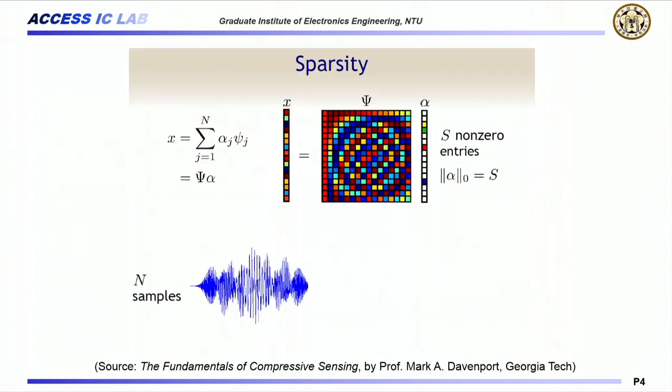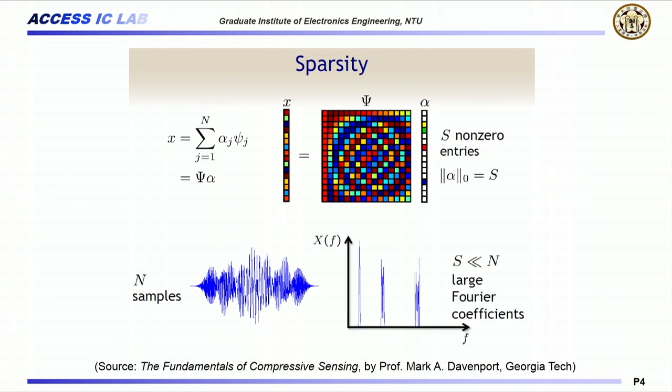One of the most important ingredients of compressed sensing is sparsity. This time series signal shows that at first glance, you won't see the sparsity. However, if you take a Fourier transform, you will see that it has a very sparse component in the frequency domain. So if a signal X has some kind of sparse representation in a certain domain, we can still apply compressed sensing. In this case, psi is the so-called sparsifying matrix, or we call it the dictionary. It's very important in our application. Here, the FFT could be the psi for this kind of time domain signal.